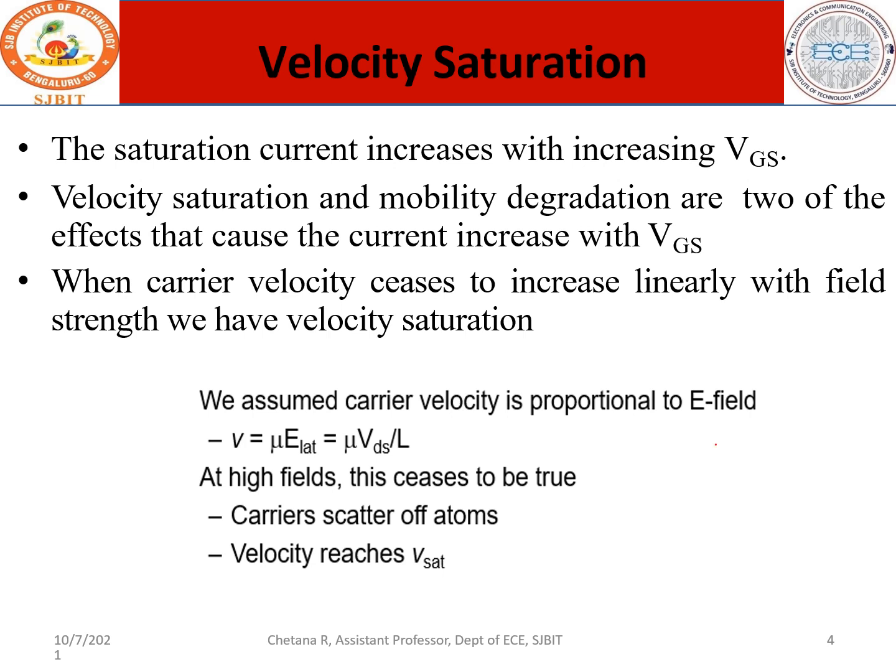If you look at this graph, this is one stage with a lesser VGS value, the second stage with slightly greater VGS, and slightly greater again. This is the representation of saturation current. You see the saturation is attained in this region itself, whereas here it is slightly different. So the saturation current increases with increasing VGS.